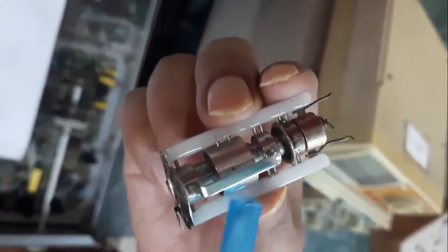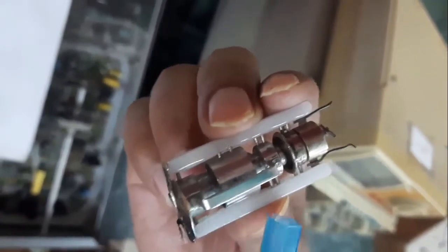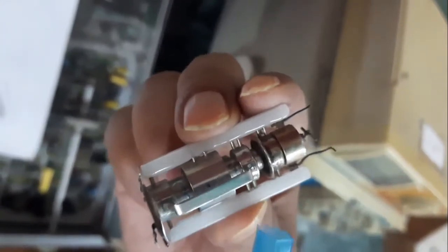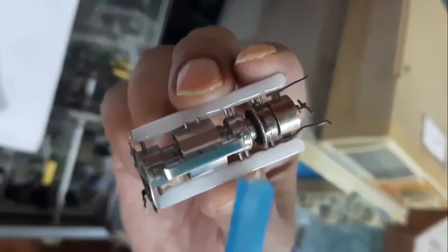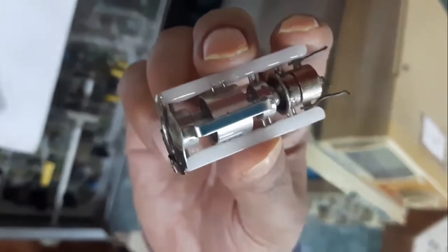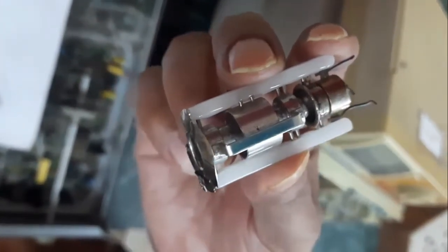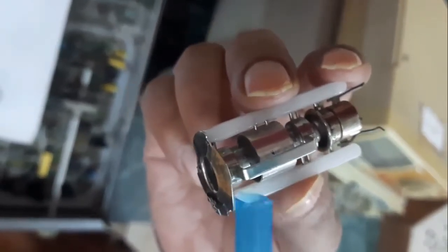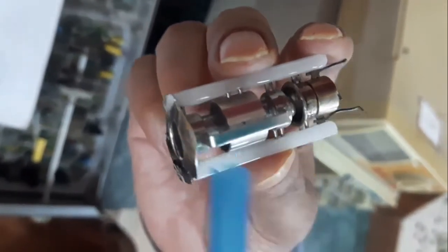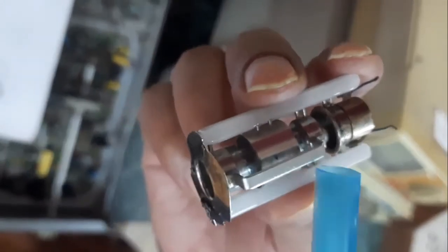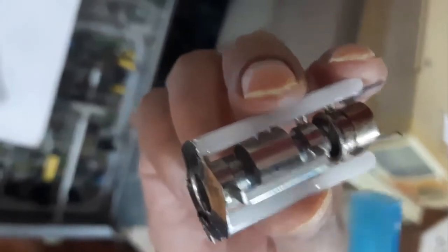A double concave lens is formed here, because of the different potentials on both sides of the focusing anode. One side of the focusing anode is connected to the pre-accelerating anode, which is at 1500 volt, while the voltage of the focusing anode is 500 volt. So one lens is formed between these two. Another lens is formed between the second part of the focusing anode and the accelerating anode. So two lenses are formed here, and these two lenses follow Snell's law for the explanation of how the movement of the electron can be controlled.